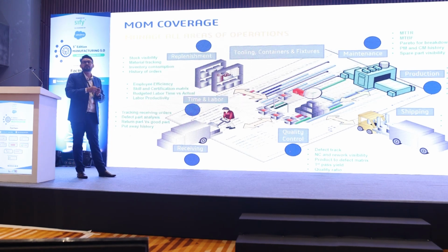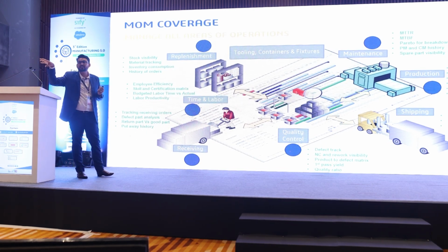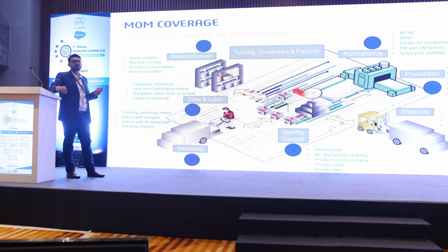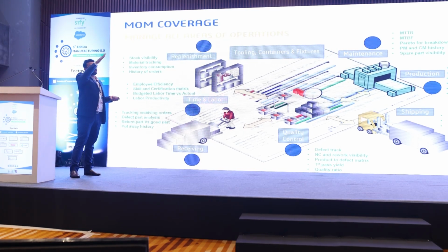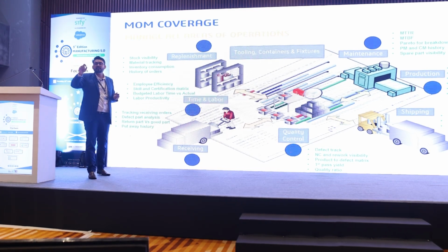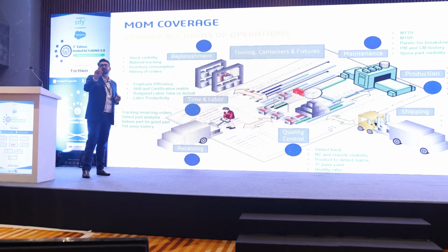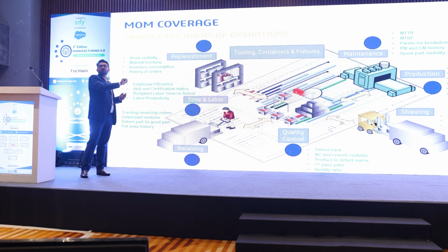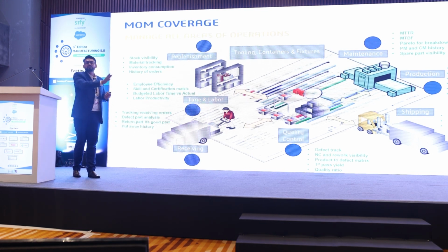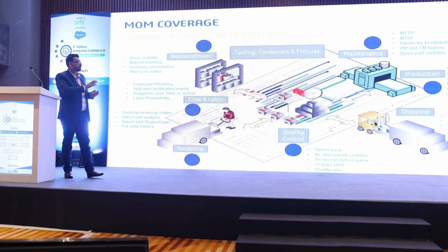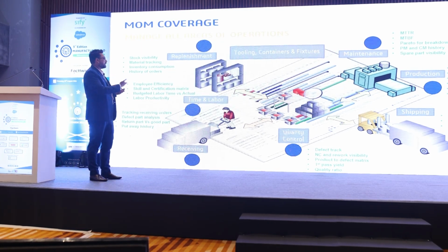So normally, your raw material starts, you get a GRN, you issue, and once you have a finished good, you just post back to ERP that we have consumed it. But in between, there is no trace of how the material is moving. Also for quality defects, every day you should have the graphs, Paretos and SPCs in a way that you can predict in one shift, from one operator, from one supplier. If you are using this lot of raw material and there is more defect, then you can do the postmortem. Otherwise, it is very difficult to actually find what the issue is. So yeah, this is everything.